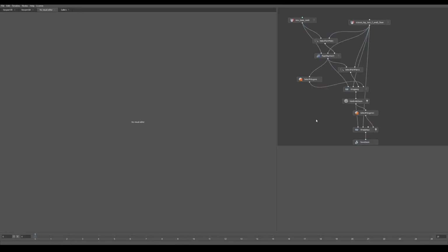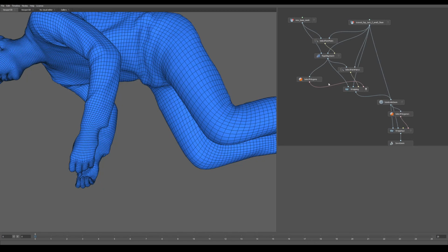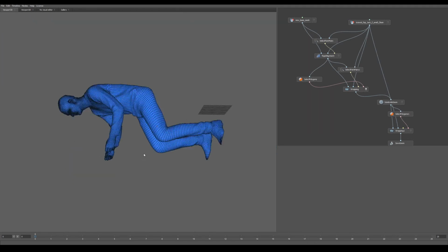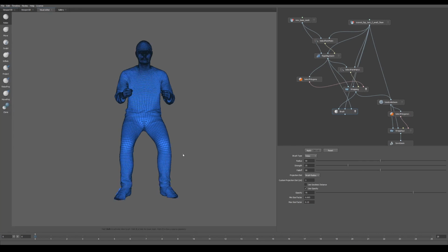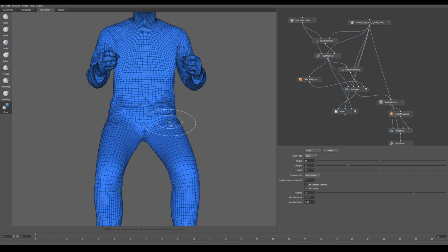This is where we can make our wrapped mesh look pretty, basically. So we don't need any of this because we're going to do our clean up on the low poly version. Okay, so let's use the brush tool and geometry, reference, and what's this one? Source. Okay, so we'll go into the visual editor, and now we can start relaxing it and cloning it to make the topology nicer as well as the model.